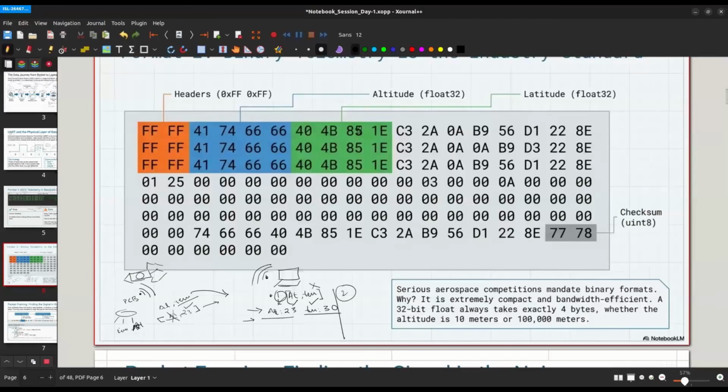But what happened is, it says the first value that I'm going to receive is altitude. Since it did not receive the altitude, it only received 23, so it's going to say the altitude is 23, even though that was supposed to be the temperature. In the next packet that was sent, the altitude was recovered, so it sent the value as 140 comma the temperature, which was 30. It assumed the temperature 23 as an altitude, and the next value it received was 140, even though it was from a different packet and it meant altitude. The GCS decoded it as 140.